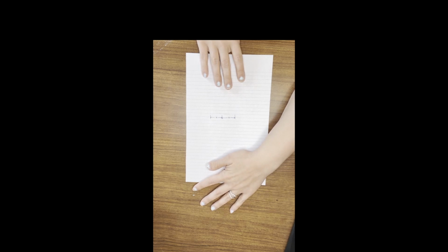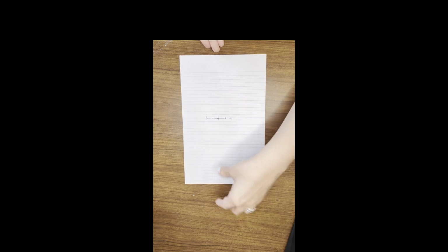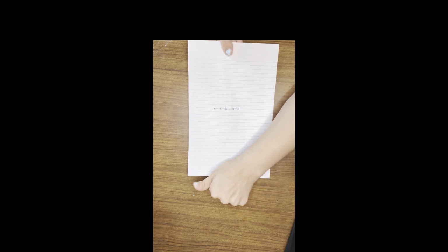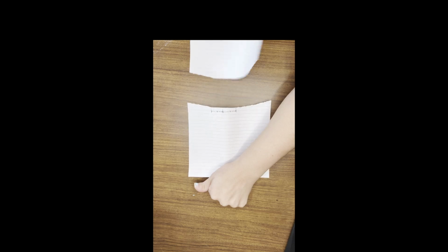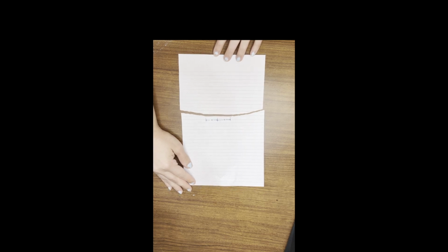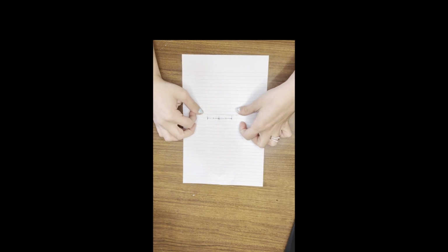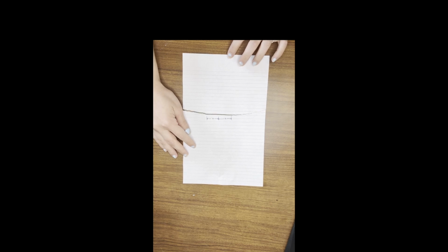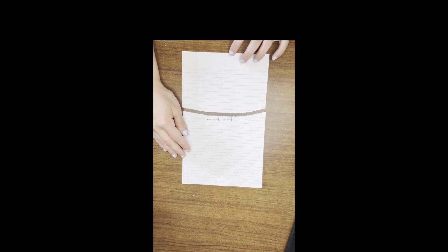And that stress intensity, K1, is what we've just defined. So if I pull on this thing hard enough, let's make sure it still tears at the edges. It does, right? So we can see that we still have a maximum stress at these corners. That's where our crack starts on both edges, but it's not equal to infinity. So we need some other way to think about this.